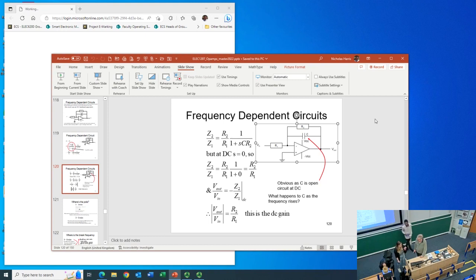So on the Argand diagram, it can't just be on the y-axis. It has to have X and Y. The Argand diagram is plotting the S number, and the Z direction is showing you the magnitude response. So the magnitude of 0 is up here somewhere, because it's a three-dimensional plot. It's a surface plot.